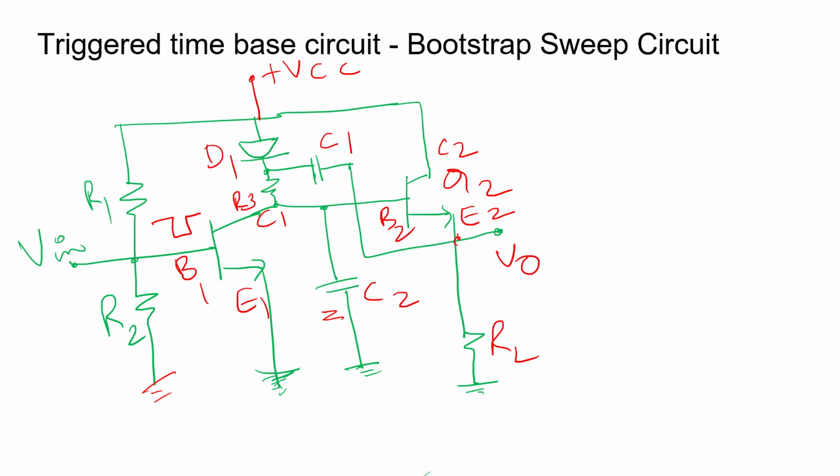After the end of the trigger time, if the negative trigger given to the transistor Q1 is removed, then the transistor Q1 will enter into low impedance state by default and acts as a short circuit. Once again, the capacitor C2, which is in parallel with the transistor Q1, will discharge itself completely. So during the restoration time, the terminal voltage of the capacitor C2 will drop sharply to zero, and the same will happen every time we give the input.